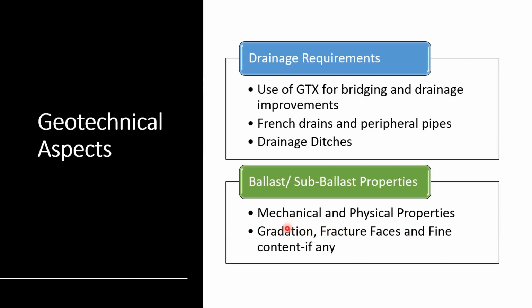And you have to tweak your gradation a little bit to make it reflective of the available quarry that you have on site. Fracture faces increase angularity and ensure interlocking friction within your ballast and sub-ballast.